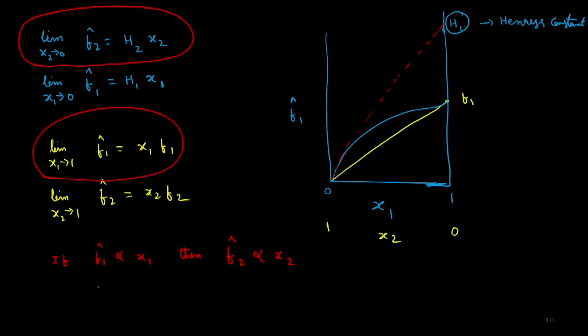The constant of proportionality here will be the pure component fugacity at one limit, as x1 goes to 1, it is almost pure 1. We have infinite dilution of 2, and the constant of proportionality at infinite dilution, we are going to call the Henry's constant for 2, H2.